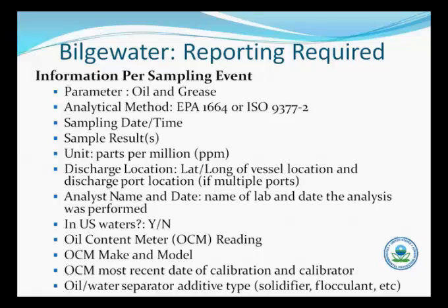So assuming you've taken your sample, done your preservation, and gotten it to the lab within its holding time, now the lab has reported its results to you. At this point, you'll be reporting the results to EPA, and you should know all of this information based off of either your field notes, your chain of custody, the copy that you've retained, and the analytical results from the lab.